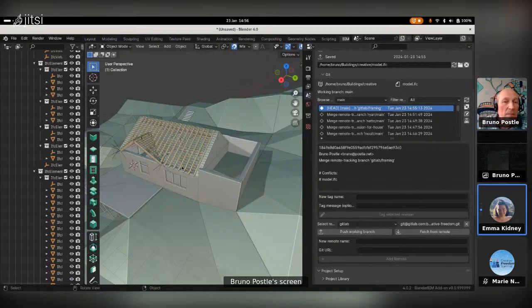Another question just came in for you. Are there any common mistakes or errors you see using this process? So if an object's been deleted in both branches and I merge, then that's fine. It'll be deleted in the result. If an object's been modified in both branches, then quite often we can merge it, even though it's on the same line of text, because IFC is so structured.